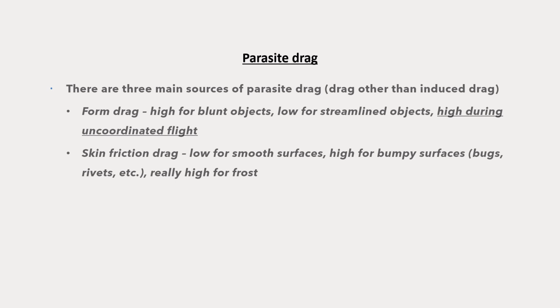One thing that really makes the skin friction drag high is frost. So if you're in a situation where frost has formed on your wing surfaces overnight, it's really important to get that frost melted off before going flying.